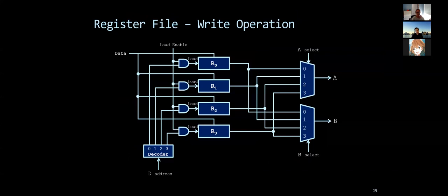Okay. So in a register file, we need to have a read and write operation. So this is a very schematic implementation of a register file with just 4 registers. As you can see here, there is a part that enables the write, right? This is the part that loads the values into the registers, with some decoder that decides which register to put it in. As you can understand, the more registers I have, the bigger this decoder is, right? It starts to add to latency, right? So if you tell me, give me a gigabyte of registers, the decoder would be humongous.